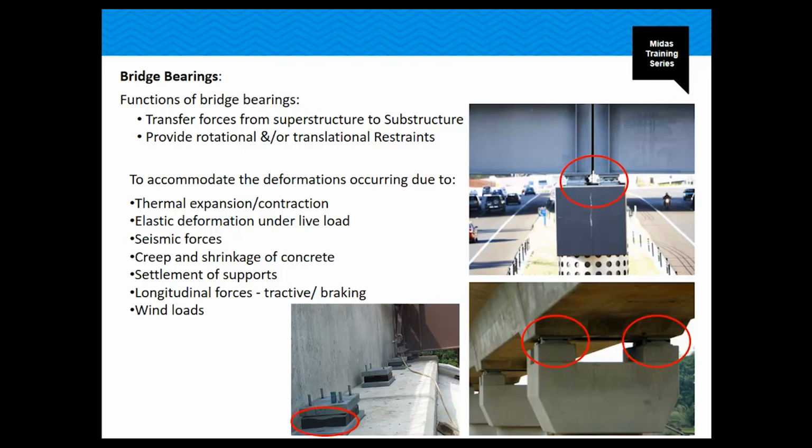These deformations occur due to various effects, such as thermal expansion, elastic deformation under live load, seismic forces, and also wind loading, settlement of the supports, and the creep and shrinkage of the concrete, depending on the type of material and the location of the project.